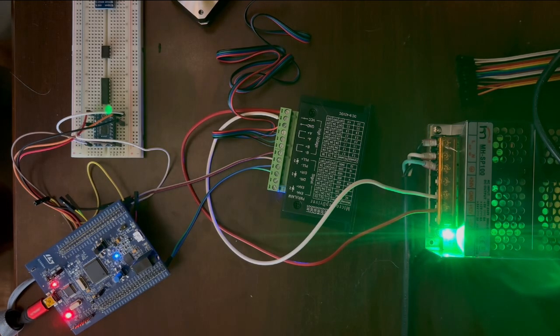That requires figuring out how many pulses will make it move how far, and how fast those pulses need to come to move a certain degrees per second. So we need to figure out pulses per degree. That's pretty easy, since right now it's 1600 steps per rotation. So 1600 pulses are required to move 360 degrees. We can do that math pretty easily.